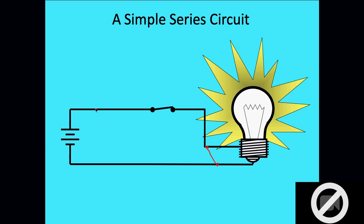So what happens if you have a circuit with, let's say, a 5-amp fuse, and it's blowing on and off, and you decide, okay, we'll fix this problem, and you pull a 10-amp fuse off your truck? What could happen in that circuit? Well, depending on what wiring you have, you're going to overheat your wiring and it's going to cause a fire. Yeah, that's my point.